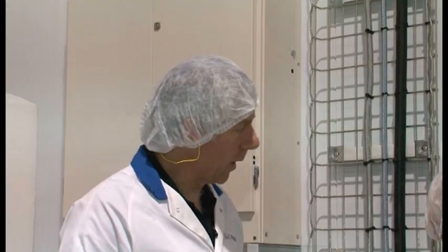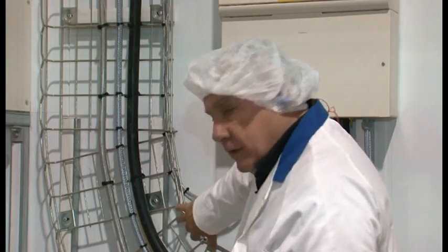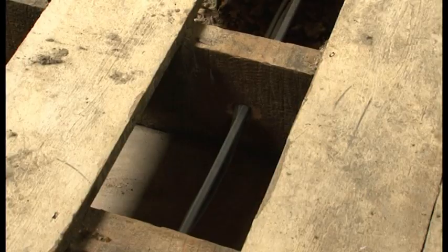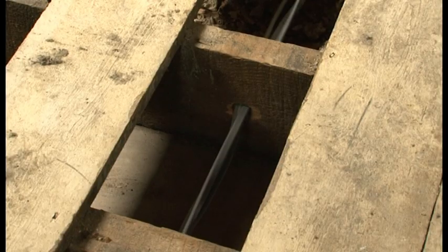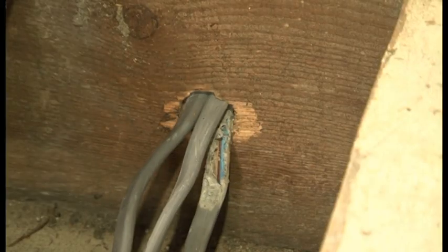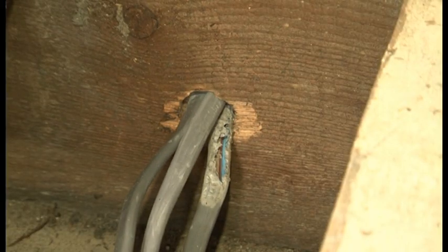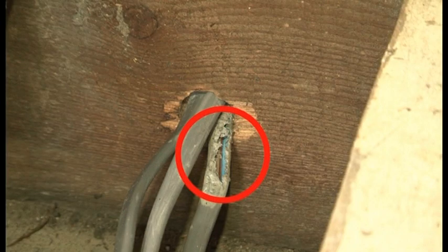And what are some of those ways, Tony? A common example can be damage to the cables caused by being pulled across sharp edges of trunking or basket systems, especially where the edges have not been deburred properly. Another one is where a cable is being run through holes in joists, already containing other cables. If it's pulled through too fast, the friction can cause the sheathing and in extreme cases, the insulation on the existing cables to chafe or even melt, exposing the live conductors.